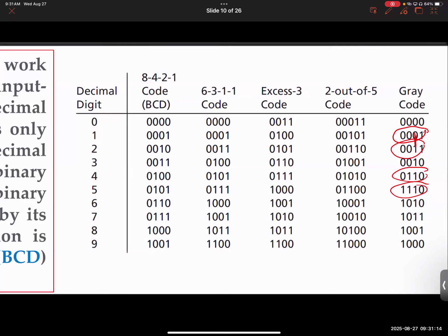This is called gray coding. And this is deliberate because oftentimes when you try to achieve better sensitivity between neighboring options, if there is just 1 bit change, that is often faster and more sensitive. Does that make sense? So oftentimes when you try to represent an analog input, an analog change with its corresponding decimal binary, gray coding is a good option. Does that make sense?